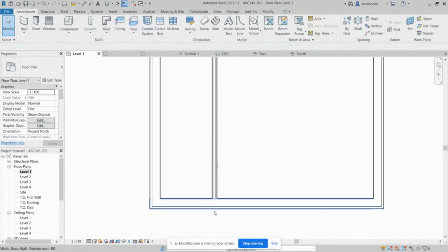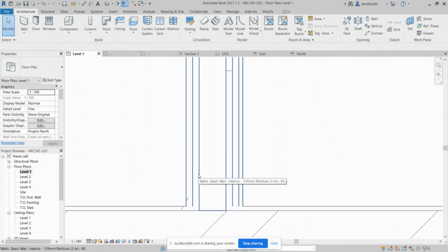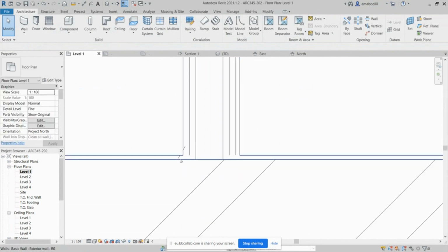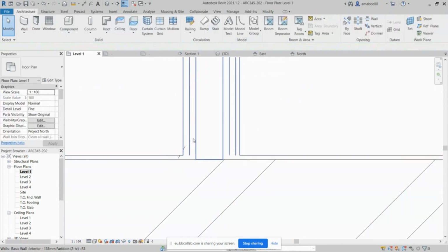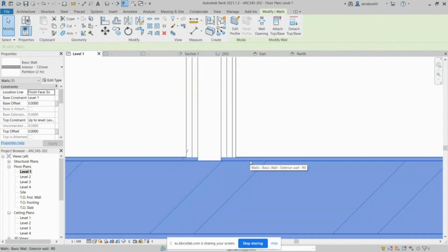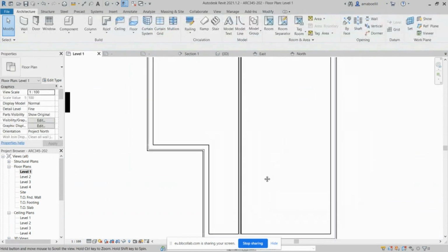So that I can make that, and you see that here is something important. Once I open this, and of course, because this wall is weird, it does have 3 layers of gypsum board, so that's why it appears like that. But pay attention that they do not close to each other. This is a layer of gypsum board for the original wall, exterior wall. It opens up with the other one, like in here. So that if I have one layer from the left of gypsum board, you would see a perfect L open up to each other because they are blended together as one material. Whereas this one is metal stud, and this one is, I think, brick. So that they do not open up to each other like this, which makes sense because it's 2 different materials. They cannot be blended in one material.